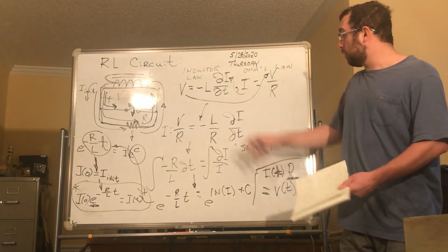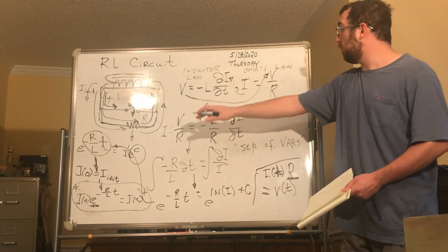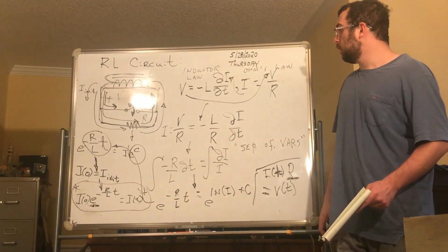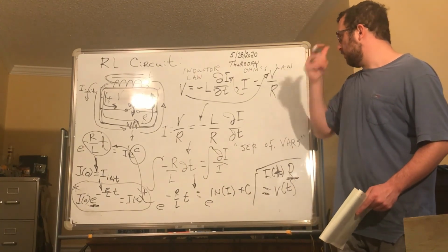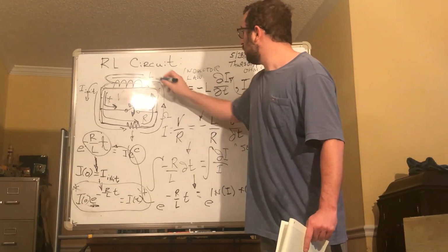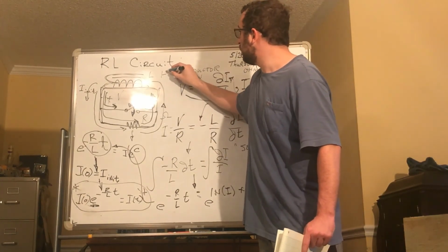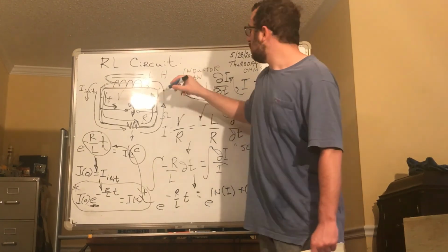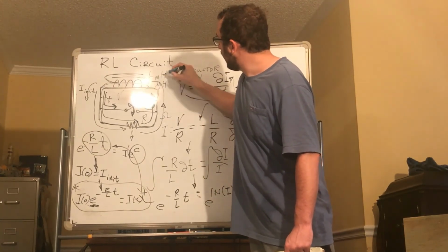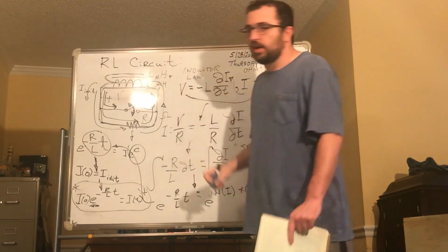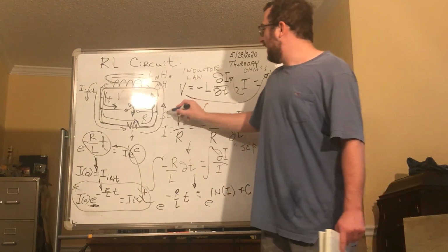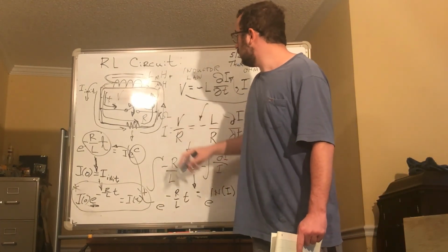But we've solved this entire circuit, the RL discharge circuit, and it's worth noting that resistance is of course measured in ohms with this symbol, and inductance is measured in henries. But typical values are millihenries or even microhenries. The actual henry is like the farad. It's a very large unit. You don't see it often. And you might have kilo ohms across here.